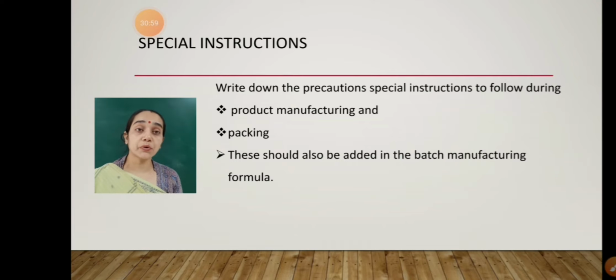So what is going to happen over here? As I have applied vacuum to the container, the product will move from the high pressure to the low pressure, then there will be splashing of the component, and as there will be splashing, the air present on the surface will be entangled and air bubbles will come into my formulation, and the presence of these air bubbles is going to hamper the stability of my product.